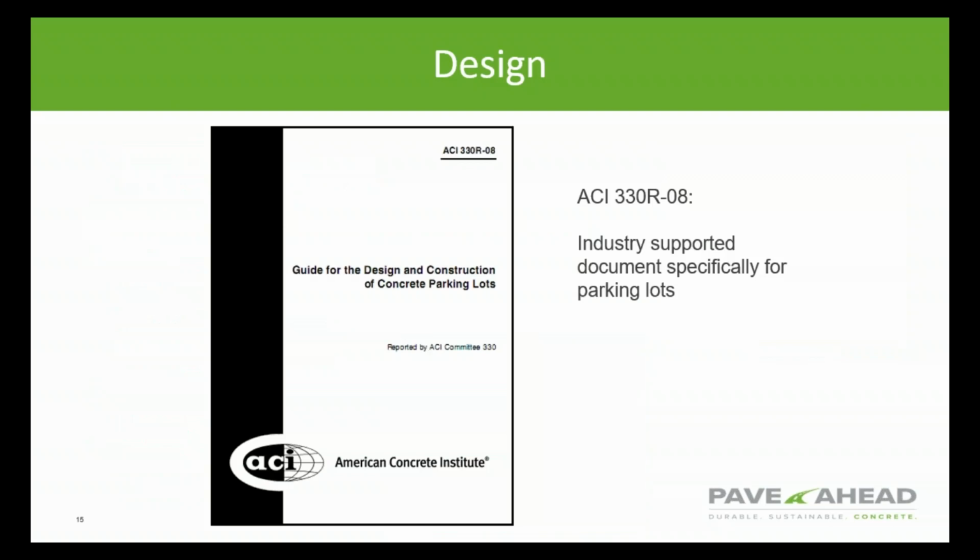Prior to 2017, this document, the ACI 330R-08, was a document that we used for all concrete parking lot designs. When looking at an industrial pavement, there's aspects of the design that are not applicable to lighter duty parking lots. Dowels, for instance, are not usually required in thinner, lighter volume parking lots, but for industrial pavements, dowels are very common.